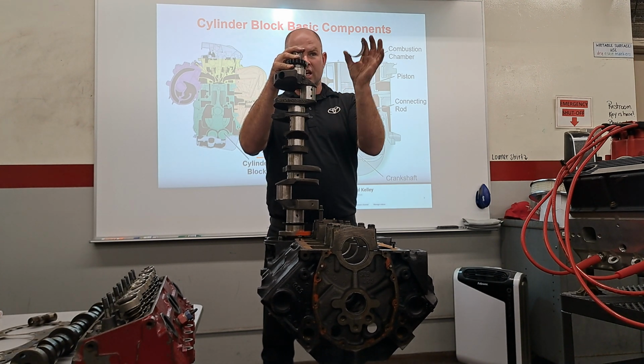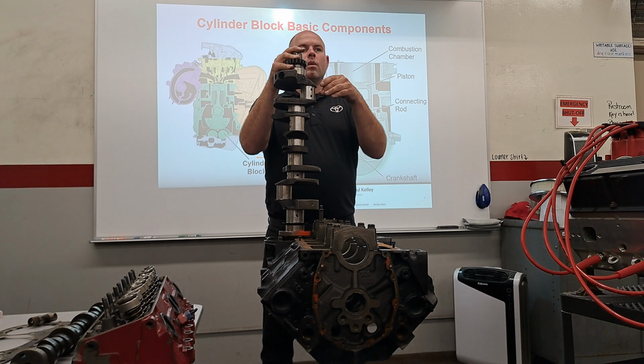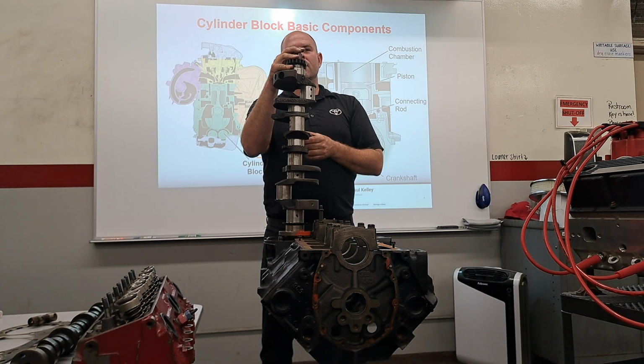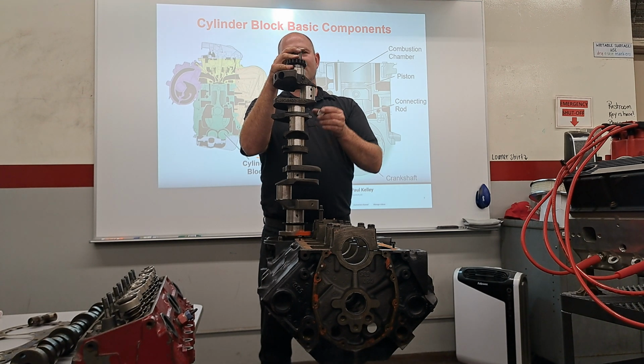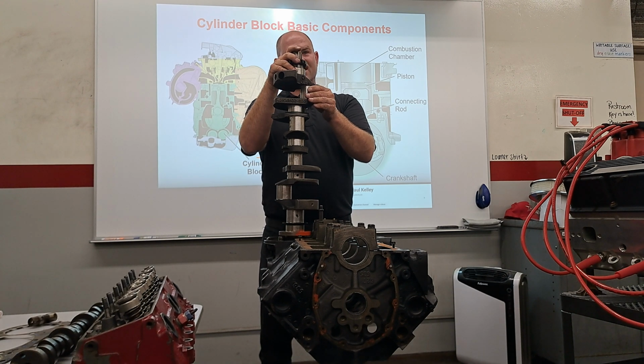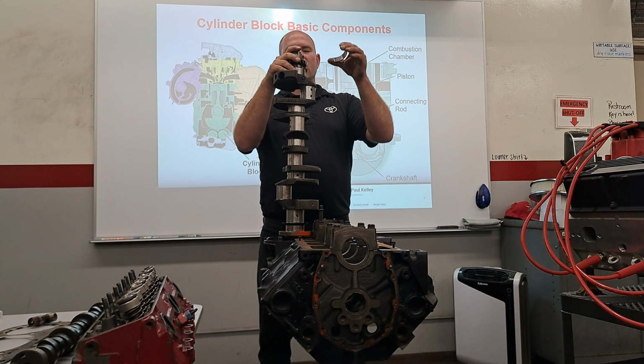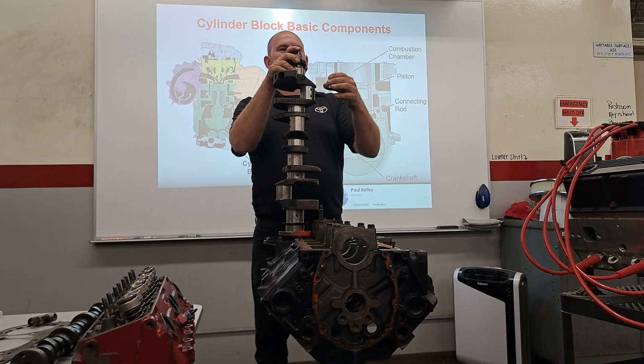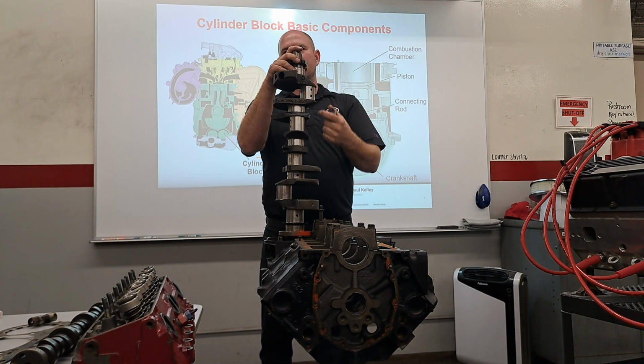What if you disabled cylinder number 1? You pulled the spark plug wire, you disconnected the injector. What would happen? Misfire. It would misfire, but what if the noise went away or severely decreased? That would kind of tell you it's the number 1 rod bearing. Make sense? So remember, the noise from a rod bearing is mostly the result of the combustion slamming it into the crankshaft. You take away the combustion, you take away the slamming.